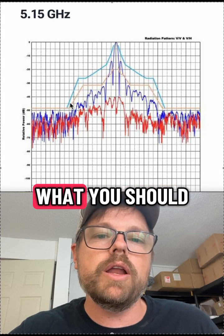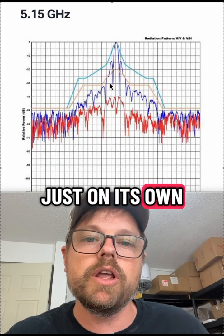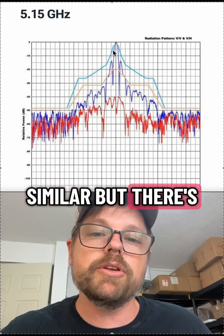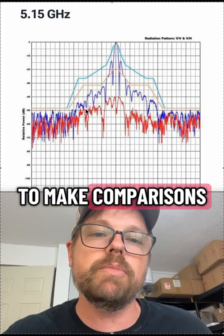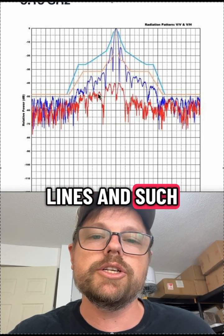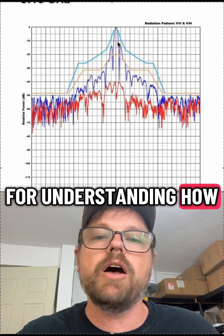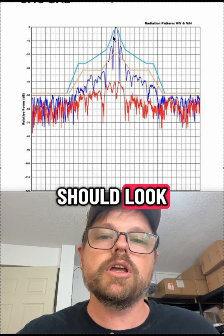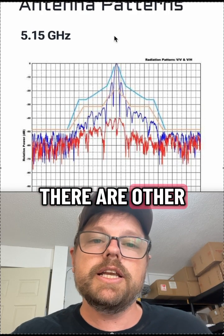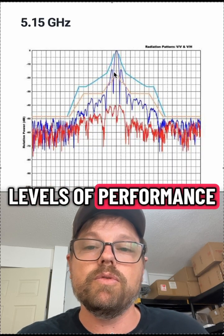It lets you know what you should expect from an antenna. Otherwise, it's pretty difficult to read an antenna pattern just on its own, know how that's going to compare to another vendor's antenna pattern that looks very similar, but there's small details, and it's hard to make comparisons if it's operating at different frequency points, has different grid lines and such. So the ETSI mask is very good as a reference, a frame of reference for understanding how this antenna pattern should look. And then you can see this is below ETSI class 2. There's other ETSI classes, of course. So you could have ETSI class 3, ETSI class 4, and then you would have higher levels of performance, higher standards.